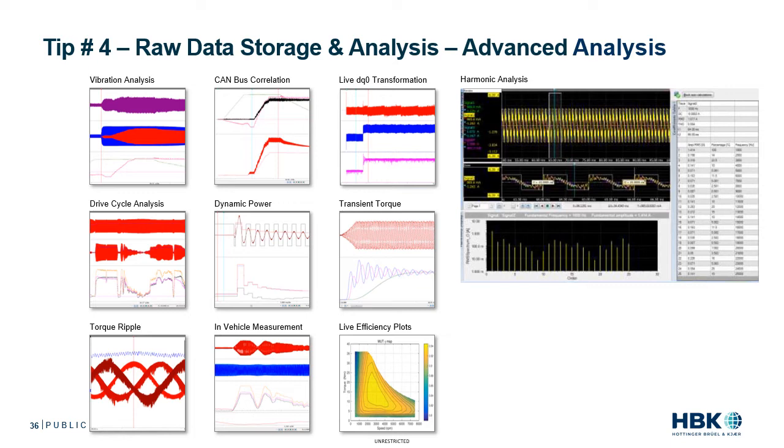Now, a power analyzer should have a wide variety of advanced acquisition and advanced analysis applications, such as vibration analysis, CAN bus correlation, live DQ0 transformation, harmonic analysis, dynamic power capabilities, transient torque, torque ripple, live efficiency plots, and much more. In fact, these features are made possible by the storage of raw data plus real-time and post-analysis equations, which should be automatically created for you based on the configuration of your drivetrain setup.